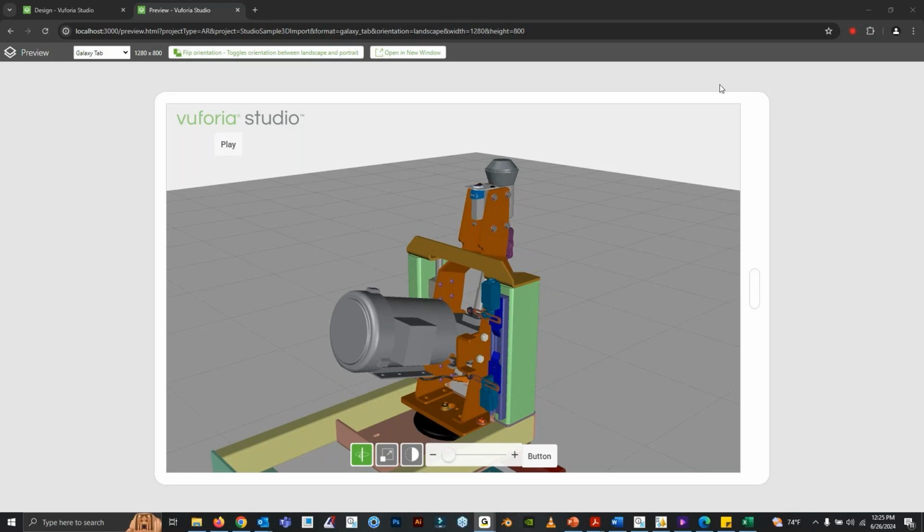So, Scott, to answer your question, if there is a revision to the assembly, I don't know how it works with other CAD software. I just know with Creo Parametric, if you do a change in there, all you have to do is re-export the assembly as a PVZ file and replace that with the previous version. When you do that and you open Illustrate that's tied to that PVZ, it will automatically update all the images as well.